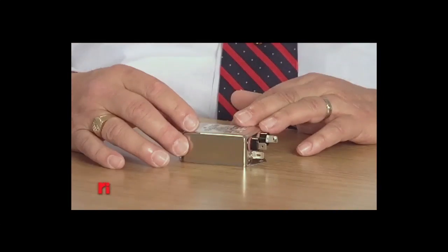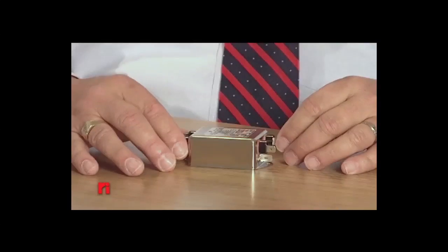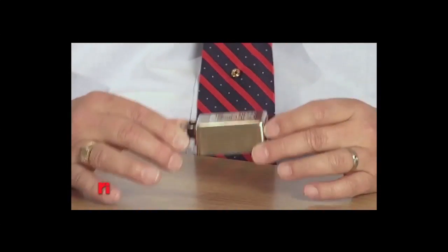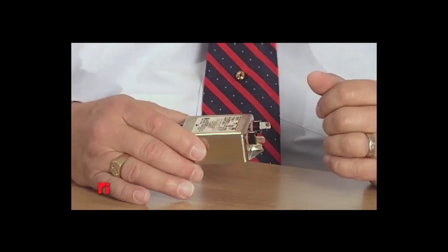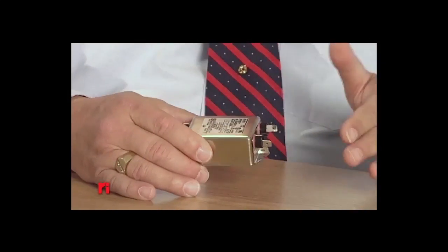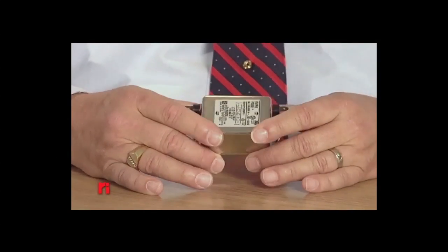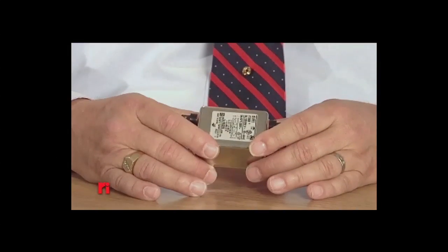Now, that is in fact the problem with this filter, because there's no separation or isolation from the input to the output. And that's why they're only effective for lower frequencies, because as you go up in frequency, you're going to get coupling. The RF energy is just going to basically couple from these leads to those leads, and it's going to render the filter essentially not useless, but much lower performance.